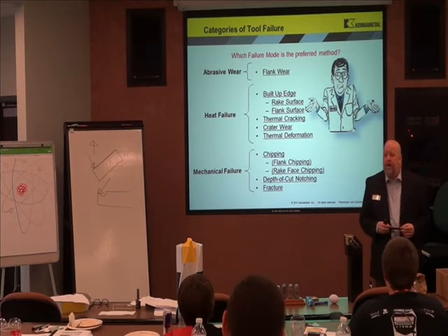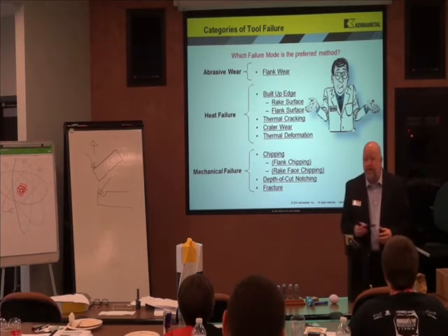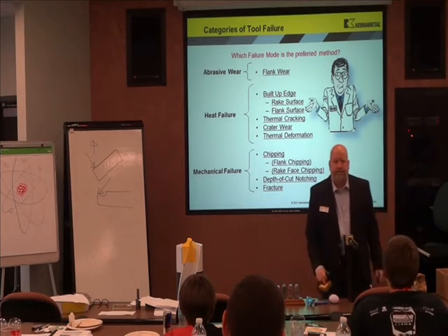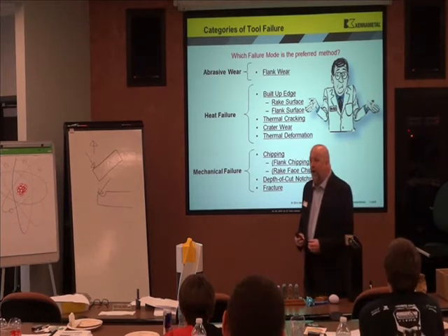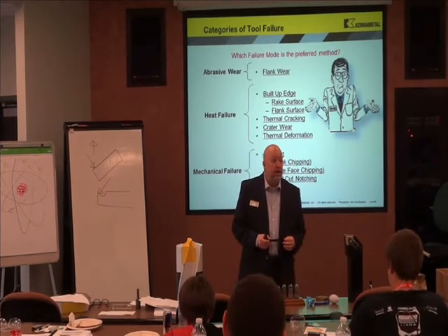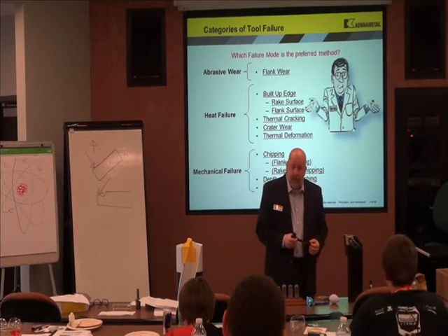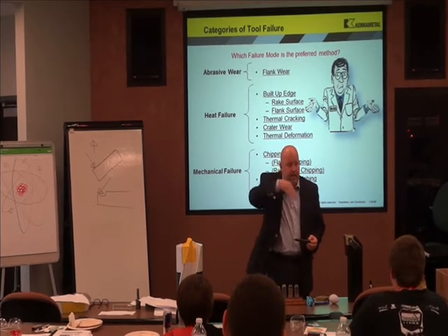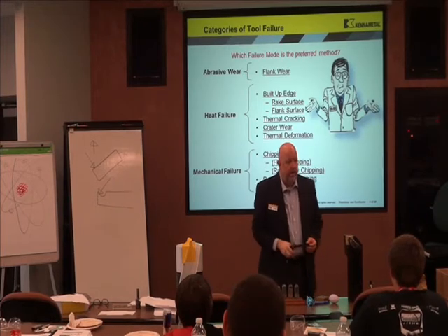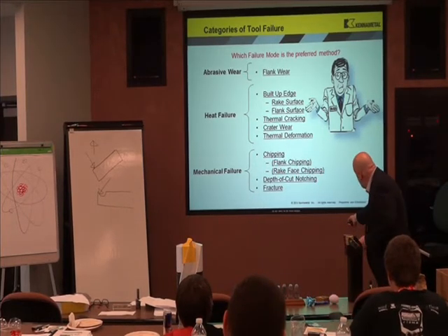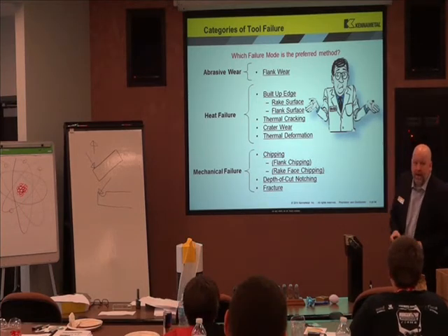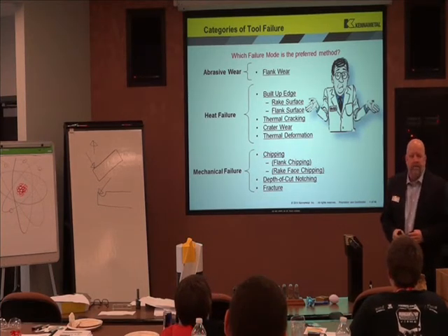I used to run the quality department for another manufacturer of cutting tools. I would get cutting tools back in pieces. They would ask me, what is wrong? You know what I would tell them? It broke. Typically, I had no idea what happened. You know why? The evidence went into the chip conveyor and out and was sitting in the hopper. Usually, when it gets down to it broke, one of these other things was happening, you weren't paying attention to it, and it broke.